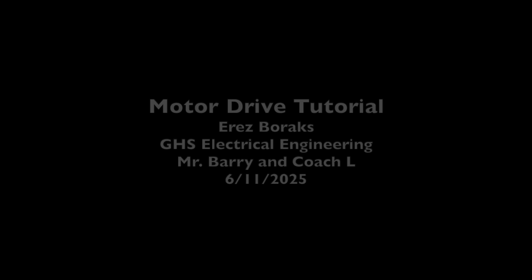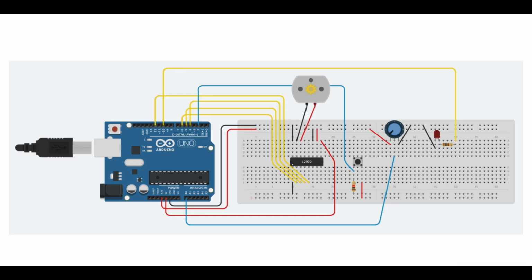So I could use a transistor to do this. However, there are a few more functions that you can do with a motor drive, such as you can have it go multiple directions, you can control multiple motors, etc. But the concept stays the same, that it is using a smaller current to allow a bigger current to pass through into the motor. And different from a transistor, the smaller current is not determining how much the bigger current will go through. That is what these digital outputs are for.